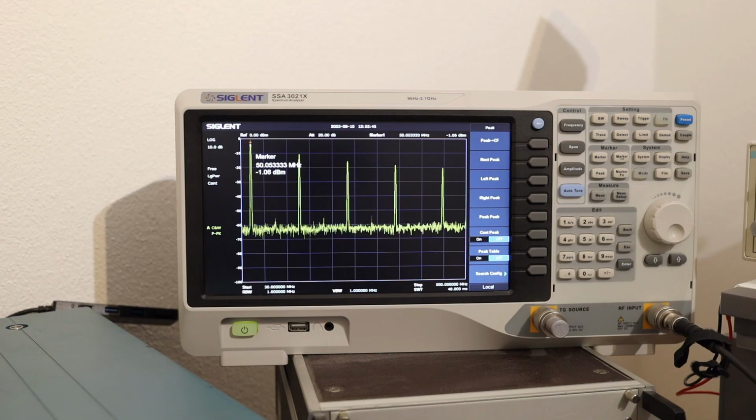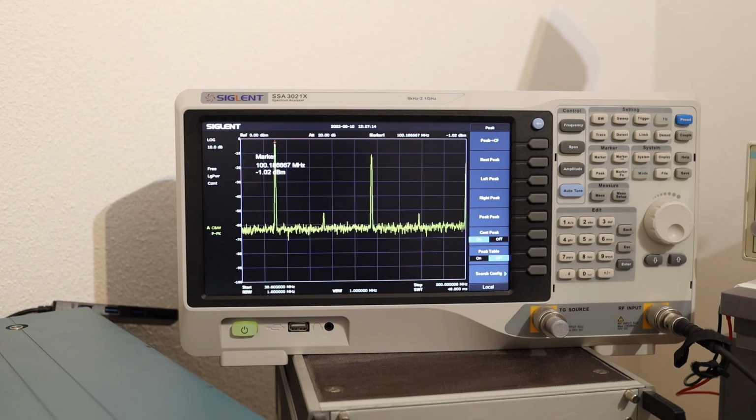The spectrum analyzer also verifies that, and the harmonics are available, as it is not completely a pure sine, somewhat of a square wave at this low frequency. So you see harmonics are available. As we saw on the oscilloscope, it was not completely a square wave, so of course we can see some harmonics. Let's go to maybe 100, similar amplitude of around -1 dBm.